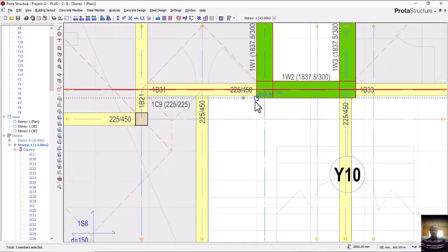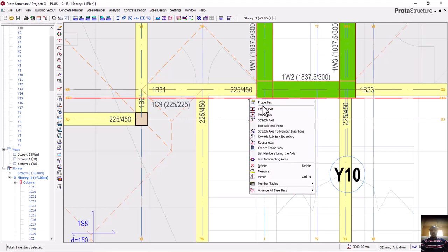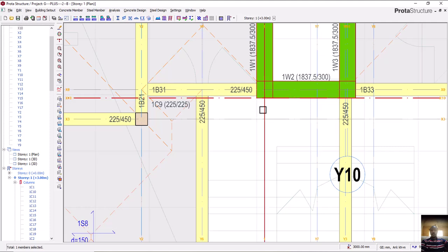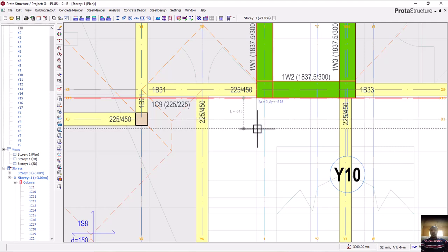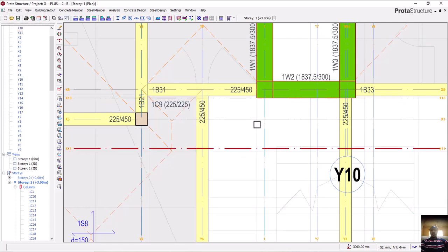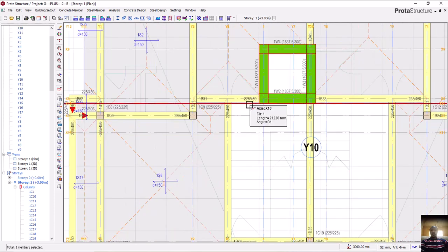Let me put it at this edge first, because that's where I measured from. So I'll now measure from here. Take this one now. From here, I'll say offset. Offset it by what? By F2. Press F2 by minus 900. Is that okay? Then enter. Can you see what I have? 900. Then click on this and delete.